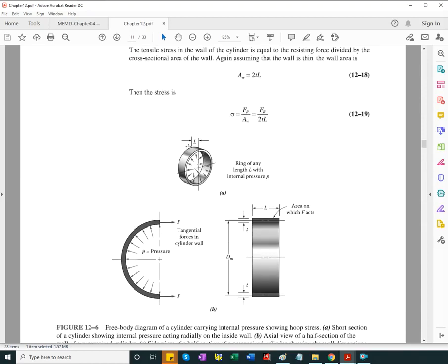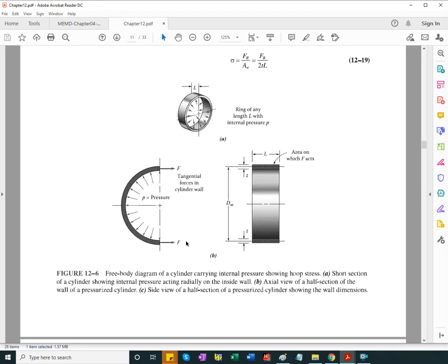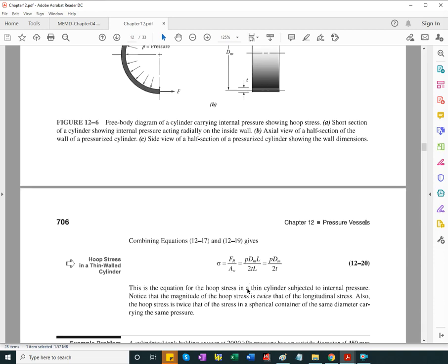Imagine now the cylinder being two halves cut longitudinally that were glued together. What is the stress upon the glue? We take that force, length times mean diameter, a rectangle, times p, and divide it by the length times thickness taken twice, because we have this area and this area of the material that gets stressed. We don't need to know the length, as we'll see it simplifies out.